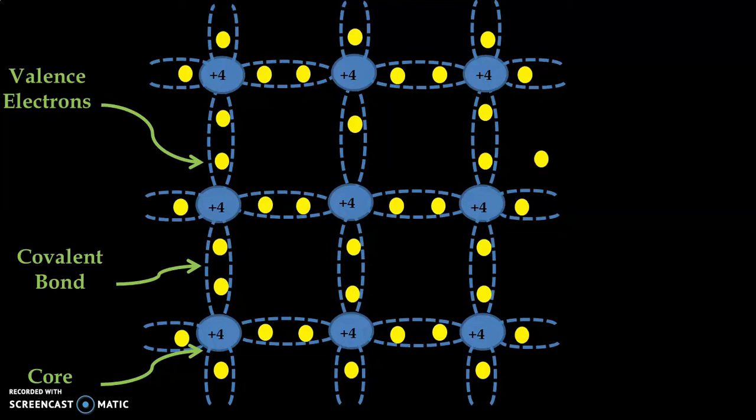It travels to the conduction band as a free electron, but when a free electron moves to the conduction band, it leaves a vacant position in the covalent bond, and that is known as a hole. So this pair of electron and hole is generated when heat energy is applied and some of the covalent bonds are broken. The generation of an electron and hole pair is known as thermal generation.